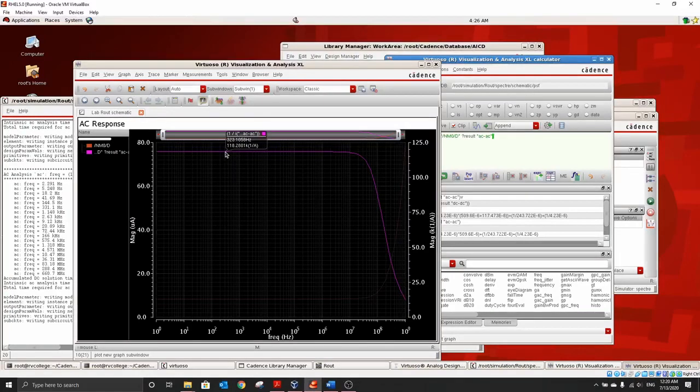So the study of output impedance for different channel lengths is meant to show that the output impedance rises with an increase in the channel length. That is the major objective for this particular experiment. We found that using a channel length of 1 micron is always preferable when we design a current mirror, because it has a higher output impedance, and any current source should have an output impedance which is ideally infinite, but at least high, right?